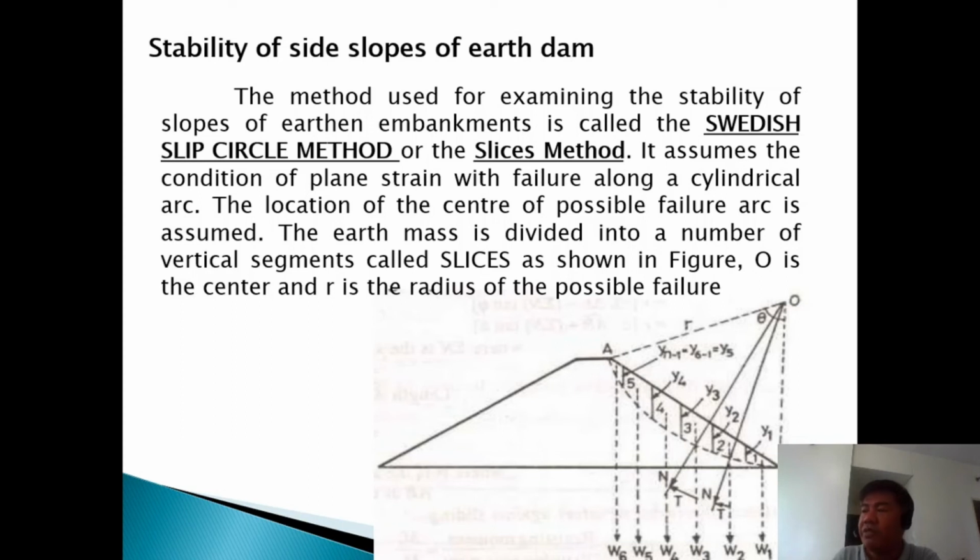That's why the method of slices came in. So what you are going to do here is calculate the unit weight, and this time, not of the whole structure, only of this critical slip surface. Before, you computed the total weight of the structure, took the moment at point B, the overturning and the resisting moment, and divided them, and then you had the factor of safety.